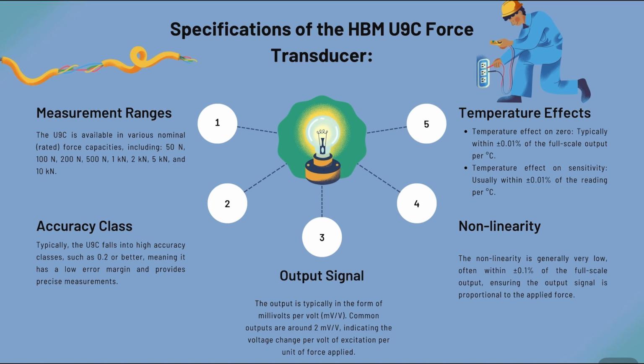And lastly is the temperature effects, which is how the temperature affects the performance of this transducer. The temperature effect on zero is typically plus minus 0.01%, which is very good. The temperature effect on sensitivity is also plus minus 0.01%. This means that temperature does not affect this force transducer much.